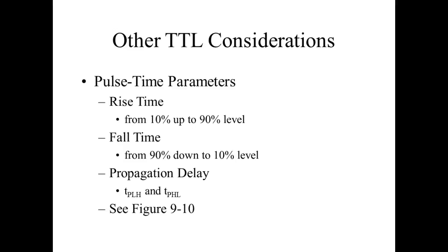Rise time, we talked about rise time. Rise time is usually not given on data sheets, but it is measured between 10 and 90% of the actual value. Rise time is the time it takes to go from a low to a high, and fall time is the time it takes to go from a high to a low. Are you okay?